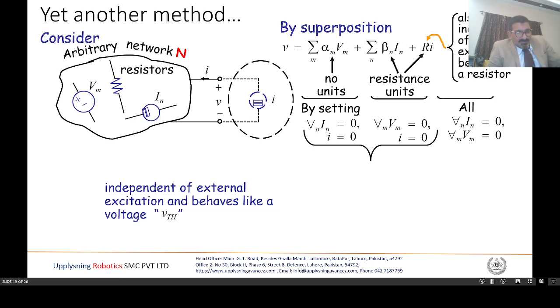The Thévenin theorem is the reduction of a complex circuit to a very simple form whenever the primary focus of interest is on the external behavior of the complex circuit. It applies to resistive circuits, and states that all effects of a linear circuit external to a reference terminal can be completely predicted from a model consisting of a single ideal voltage source in series with a single resistance.